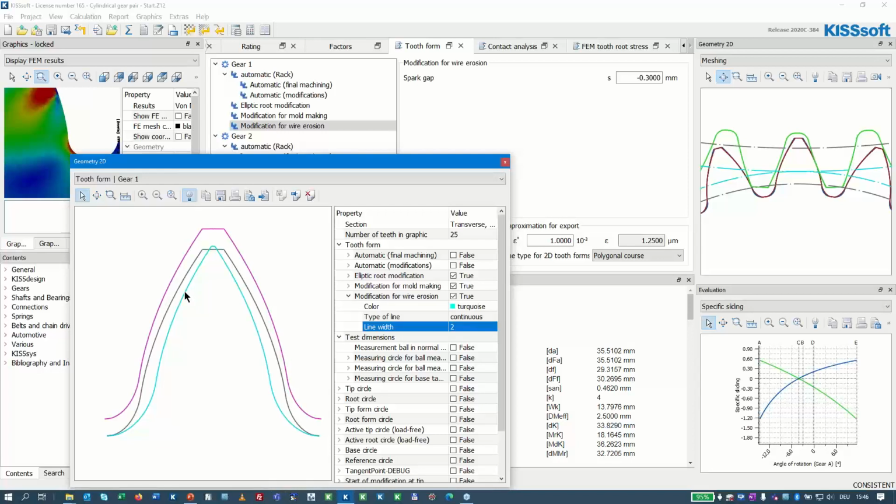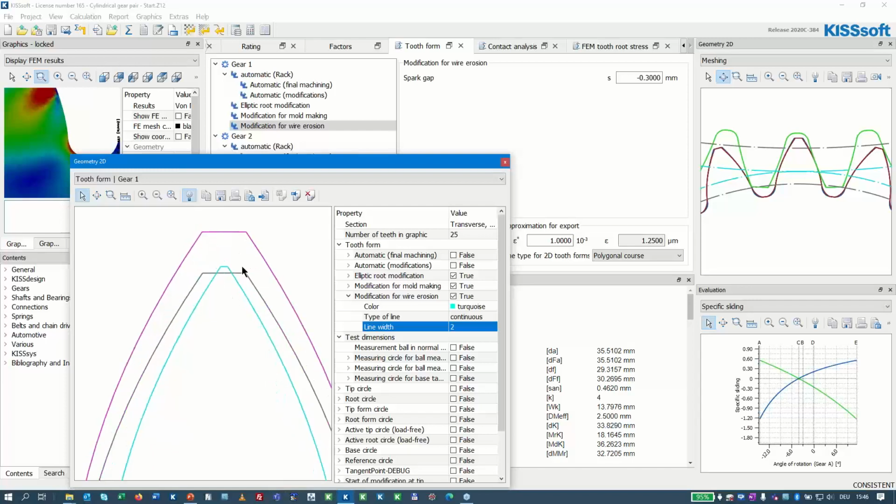Of course, in reality, the wire diameter you would choose lower. You can see fairly quickly that probably this will be a tricky area to have the wire travel. So the wire travels on this path, and in an equidistance here, this equidistance is always 0.3 millimeter. However, if the wire is here, moving on a corner, it will generate some radius up here.